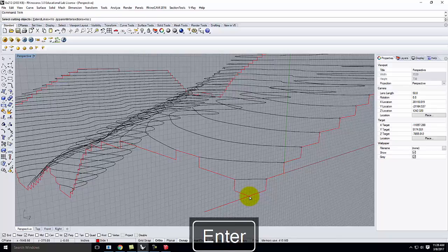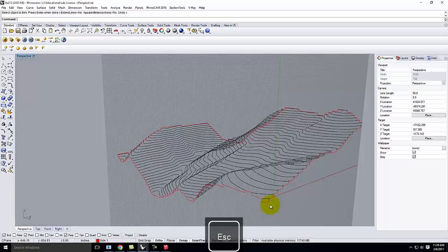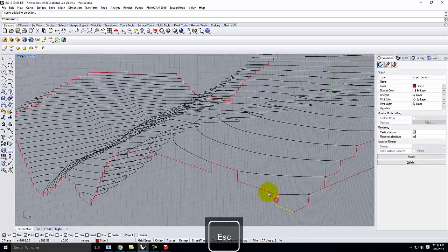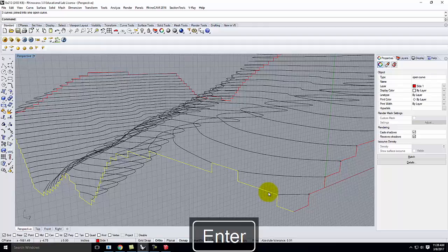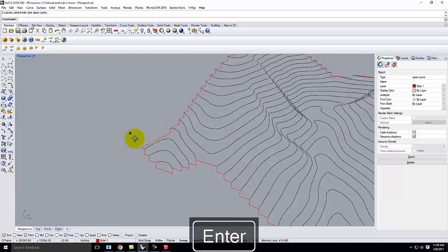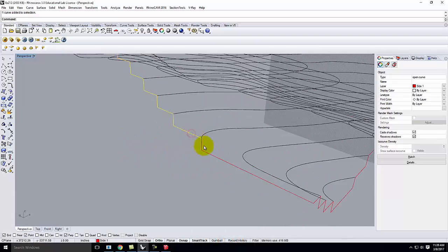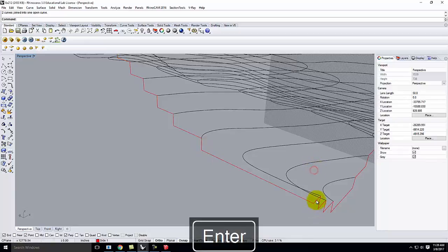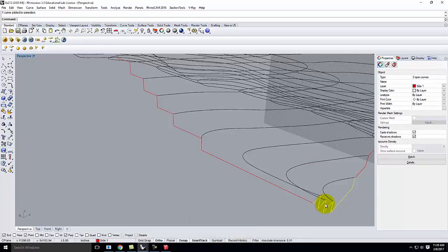And we'll go ahead and trim like that. So I do need to make sure that these are connected to that curve, and those are connected to that curve. So I'm typing join. I forgot to do that over here. Let's make sure that these are joined, and that these are joined as well. Oop, looks like I need that piece too.